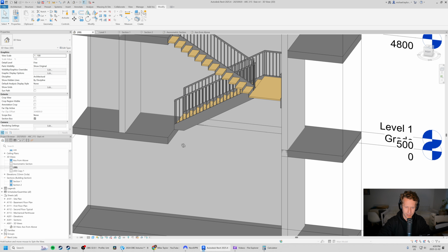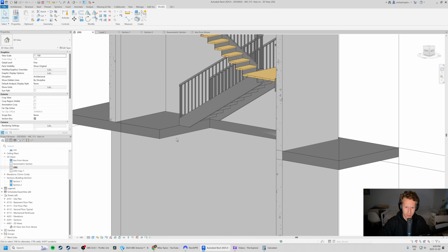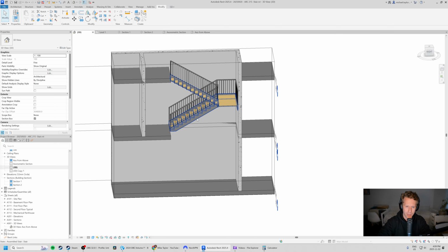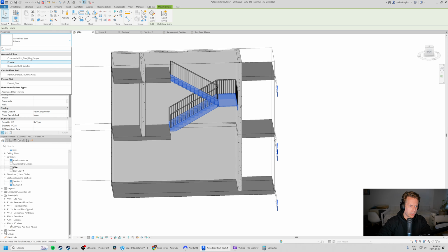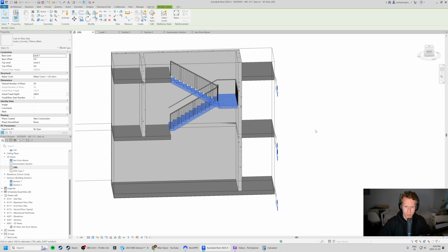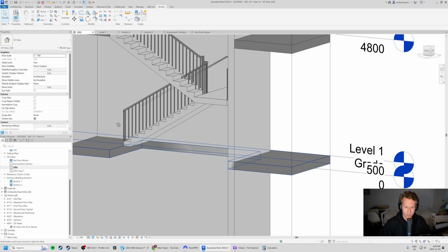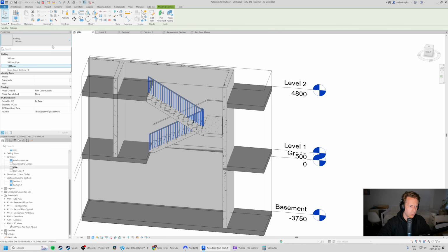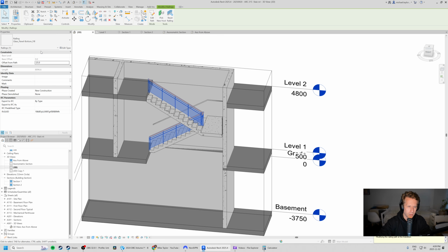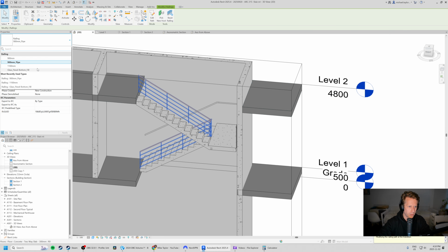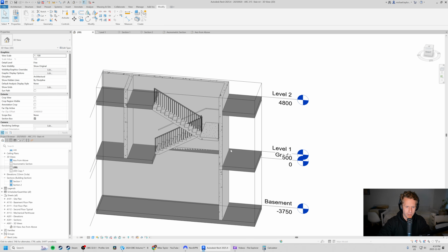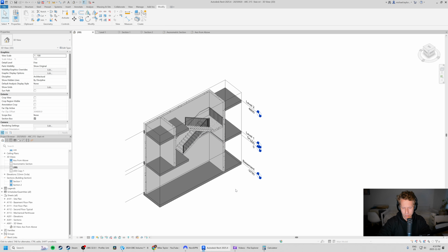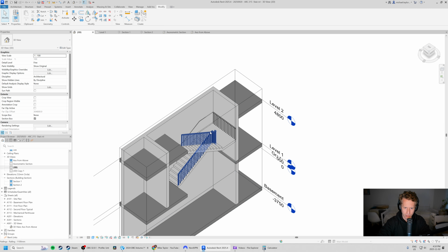You can see here, we probably want that to sit on the slab. What happens if I change this? Let's just change this real quick. In situ stair. Yeah, it's looking a little better. The railing's looking a little rough. You can see here we've got some pre-built. I don't think this is the code. Don't use this one. 1100 is probably the safest. We're going to do it that way. You know what? Let's use this stair. This is probably a little safer.